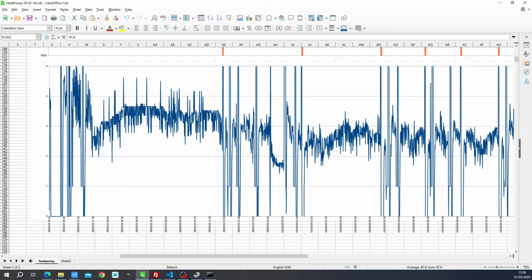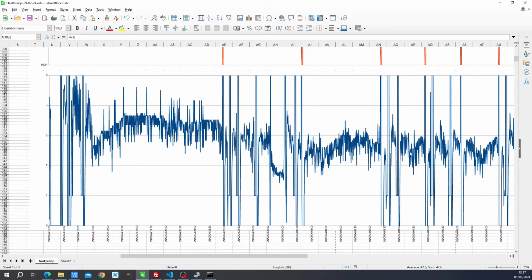So it's about 3 degrees, and then it drops down to a coefficient of performance which is about 2.5 to 3. It floats around at a temperature of minus 4. And to be honest, look at the nameplate capacity of this. It's got a coefficient of performance rating of about, I think it's 3.2 at 2 degrees Celsius, and at -7 degrees Celsius it's got a coefficient of performance nameplate of about 1.9 something. So this is right on the money.